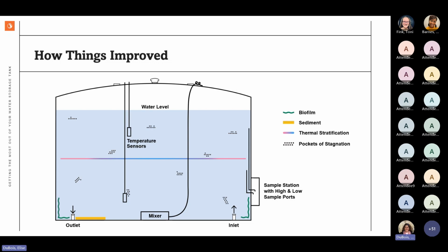And we would have determined the type of mixer to be used, active as it's powered and on 24/7, 365, and run a CFD model to determine the number of mixers. We don't need to run a model for every mixer installation, but for odd-shaped tanks, tanks with problems, or tanks that have dimensions that are extreme, so for example, a 200-foot high but 25-foot diameter tank, we would run the model. Realize that most states, provinces now require that an engineer design the mixing system in your tank because they will need to sign off on permit applications or the drawings.